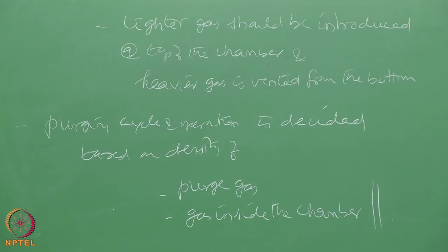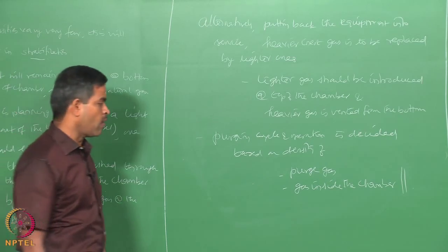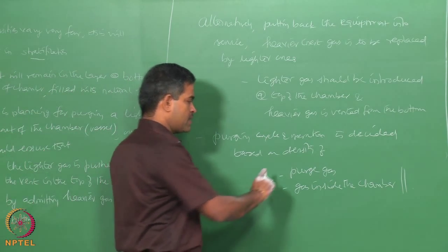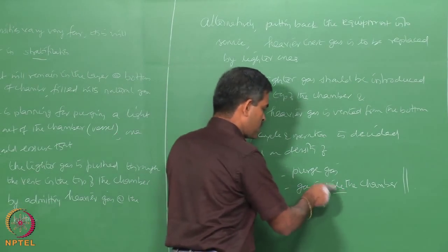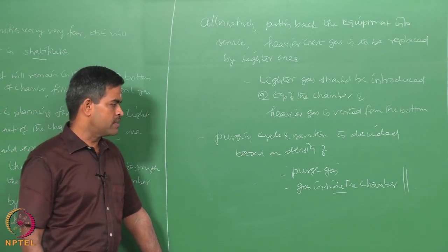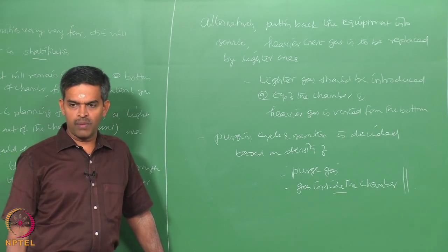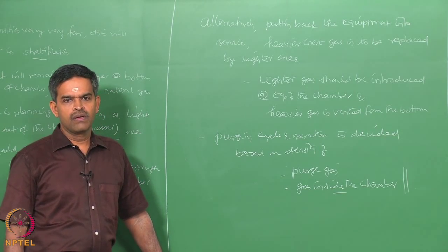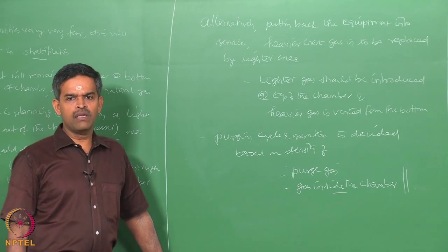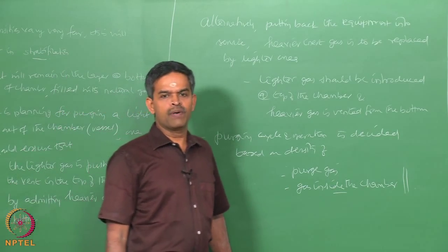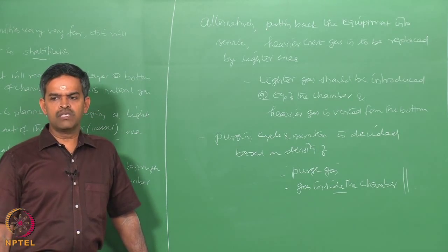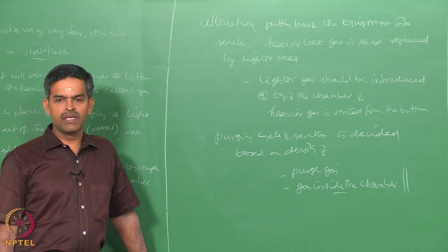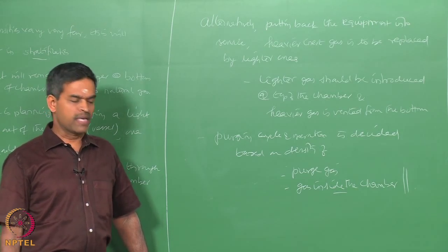So, while placing the vessel in operation or out of service, one should be very careful about operating with a purge gas of higher or lower density in comparison to the gas inside the chamber, so that the lighter one exits and the heavier one is pushed from the bottom, or vice versa. Interestingly, heavier gases like butane, propane or benzyl vapors can first be displaced downwards. Natural gas is displaced upwards, because it is lighter, out of the top vents by an inert gas, which is subsequently replaced by air.